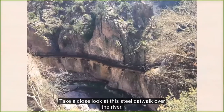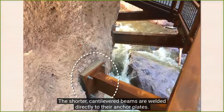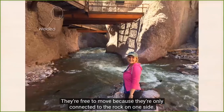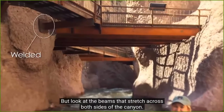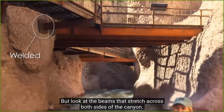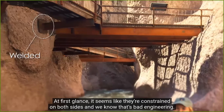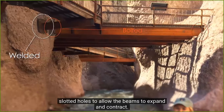Take a close look at this steel catwalk over the river. The shorter cantilevered beams are welded directly to their anchor plates. They're free to move because they're only connected to the rock on one side. But look at the beams that stretch across both sides of the canyon. At first glance, it seems like they're constrained on both sides, and we know that's bad engineering. But if you look closely, you can see that they're bolted to the anchor plate using slotted holes to allow the beams to expand and contract.